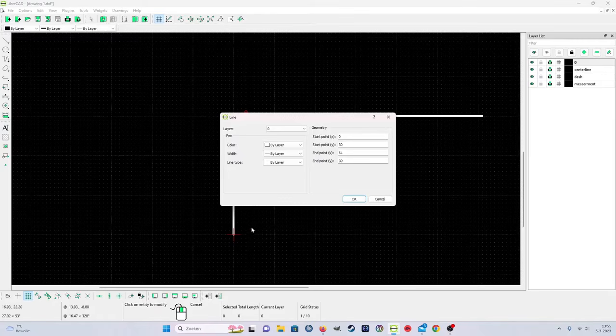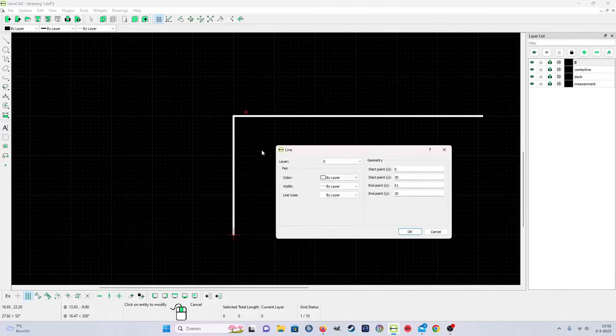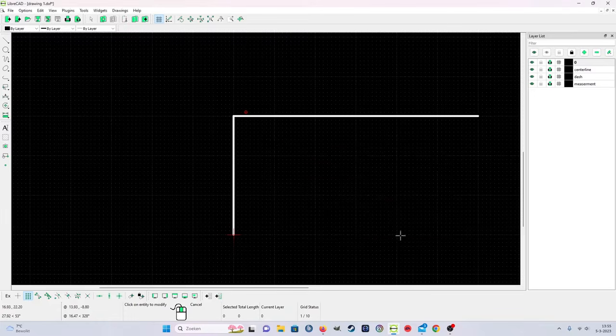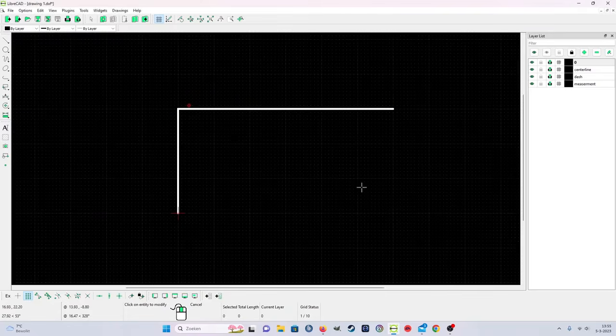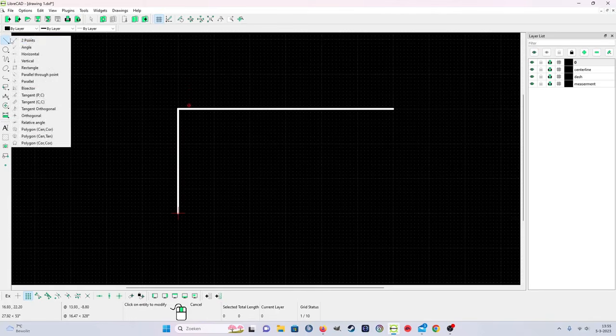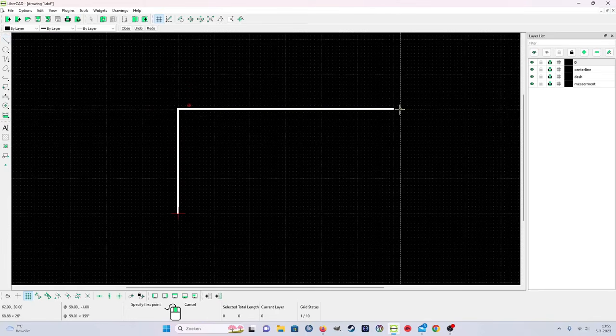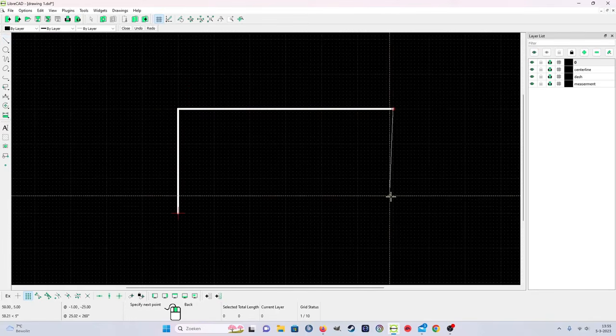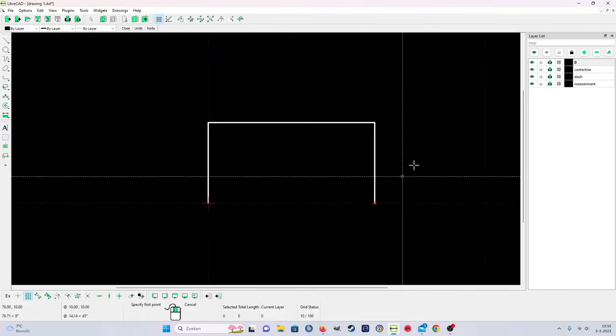And the length is from the 0 point. Wait, I can show you from here. Start point X to the end point is 61 mil, but I want to have 60. Then you change it to 60. You say okay, 60 mil exactly. That's my first part of the shaft, and I put it like this. I say okay, that's the first part.